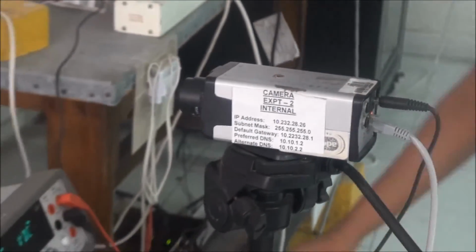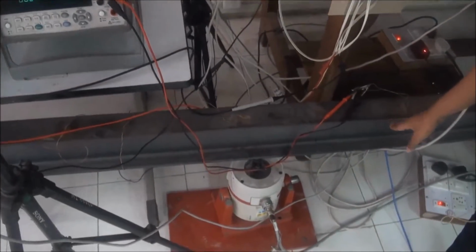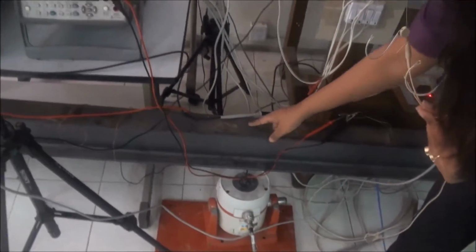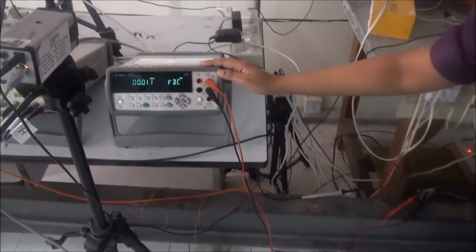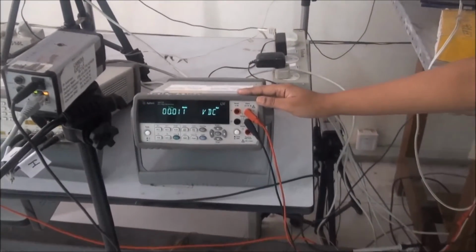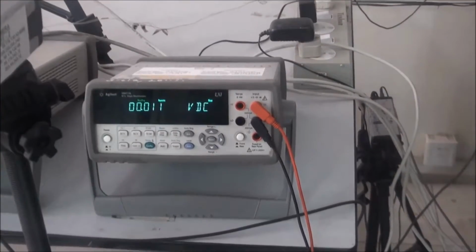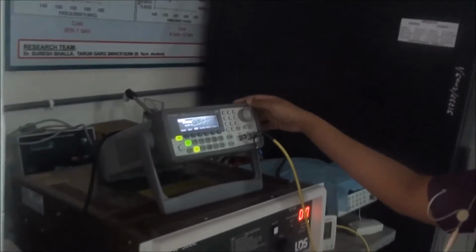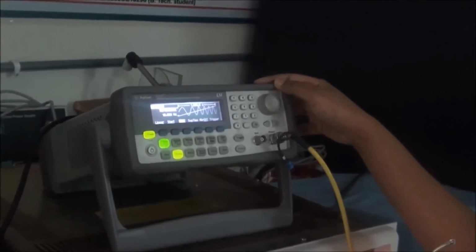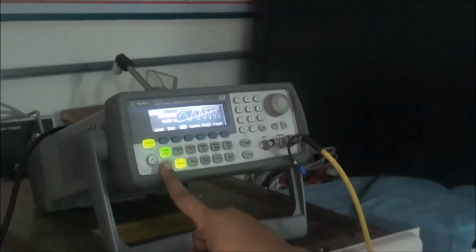And this is the experiment number 3 setup. This is a 3.2 meter steel beam where a PZT patch has been attached, and this PZT patch has been connected with the DMM, the digital multimeter, which will be connected with the vPro software via the user's account. This one is connected with the function generator, from which we will get the electrical signal as a sine wave in sweep form, and this is connected with this amplifier.